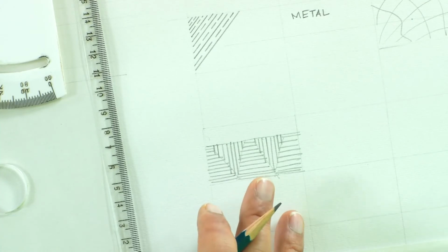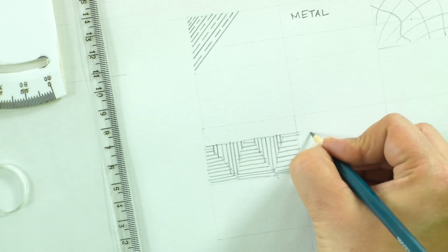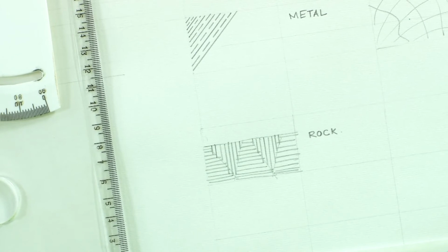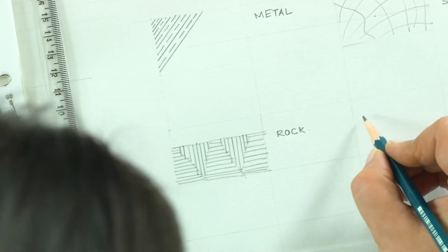Suppose there is a rock section. In case the drilling is being done and you have a very deep pile foundation which is going to be used, then how we represent rock sections is that we will have this combination of hatching, a vertical and a horizontal hatch which will be placed together. So, this is what we used for rock, and for insulation, then again we have,